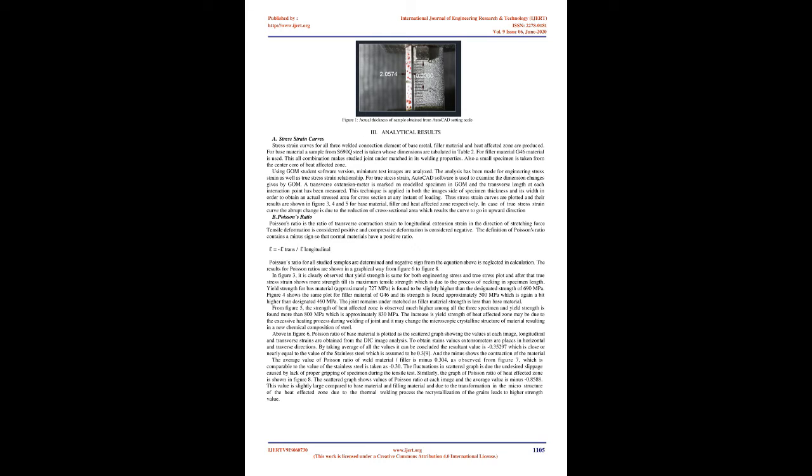Longitudinal extensometers with a length L of 10 mm are created on the image sets taken by camera 1 for longitudinal technical strain identification. Transverse extensometers are created on image data sets taken by camera 2 in the section that presents the necking and fracture, to get the cross-section change, which is needed for the true stress-strain curve. Finally, the image taken time is matched with the test machine sampling time, using Excel functions and tools, to obtain the corresponding force for each image.